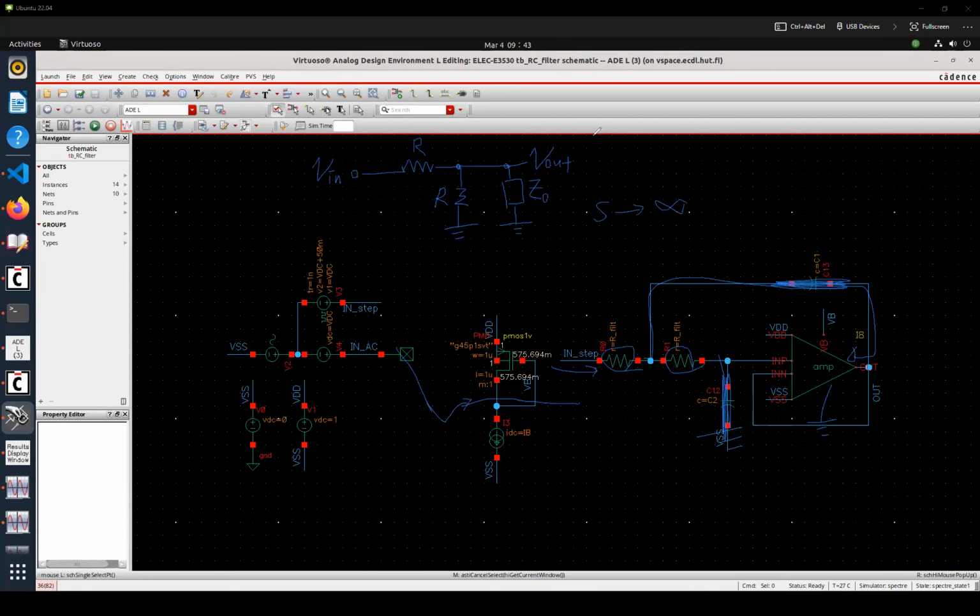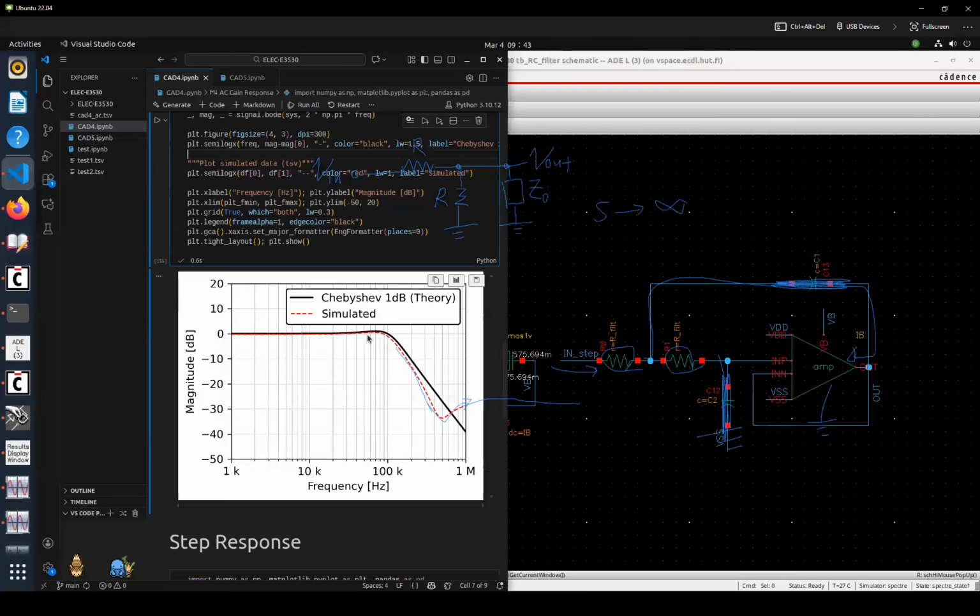So there is a finite high frequency gain. It doesn't go to negative infinity, but it touches the limit. That is the effect you are probably experiencing at the tail of the high frequency part. But the most important thing is how well it matches the expectation around the corner frequency. If you successfully matched this behavior around the low pass filter corner frequency, then everything is good.